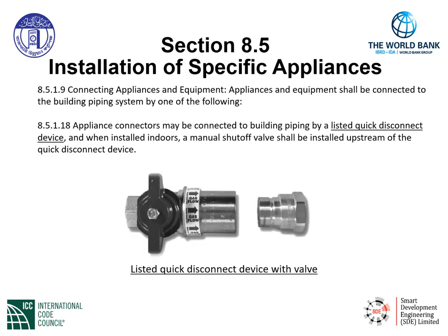Connecting the appliances and the equipment, we also have the ability in 8.5.1.18 to utilize what we call a listed quick connect device. With respect to the graphic that's shown, you can see that this is a two-piece system. On the left-hand side, we have the valve and mating quick connect device.